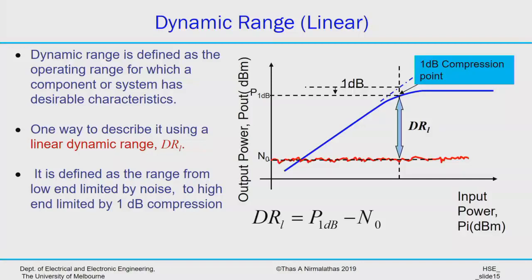And so what I was trying to lead to before, there seems to be a sweet spot where the intermodulation is not there, and I can get almost linear gain. That's where I wanted to operate. And in electronic design, there is a parameter often used to characterize the safe operating range for your system. It's called dynamic range, all right? The dynamic range, just be careful, it actually means different things depending on what you design, even within electronic design.